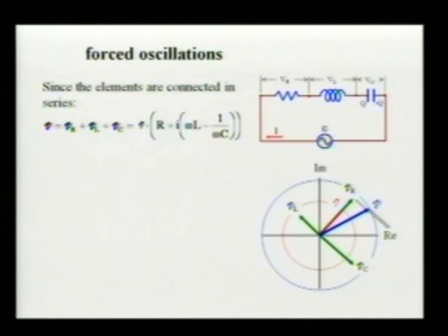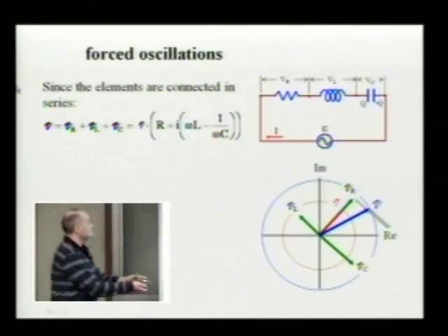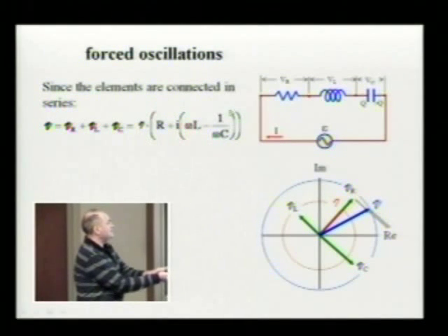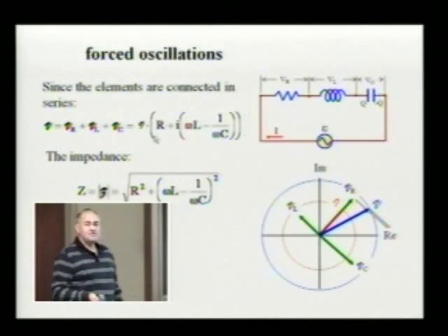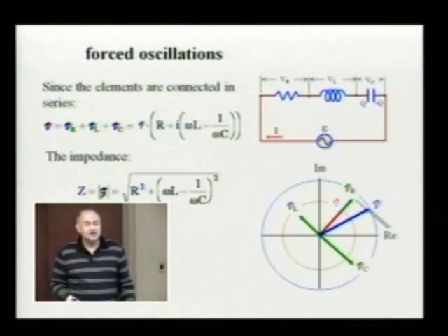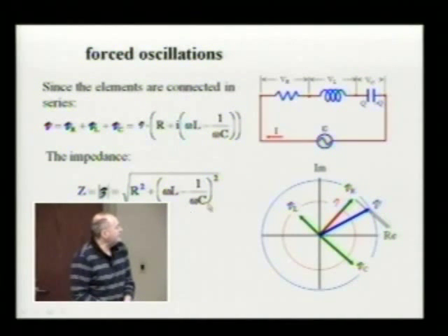Look at that now. Are we happy? It's the same thing as we see over there, right? Do you see now the mechanism, how the phases really work? Now, how about if we find the phase angle? Where should I look on the phasor diagram for the phase angle? Where is it? Between the red and blue line. The angle between the red and blue line is the phase angle.